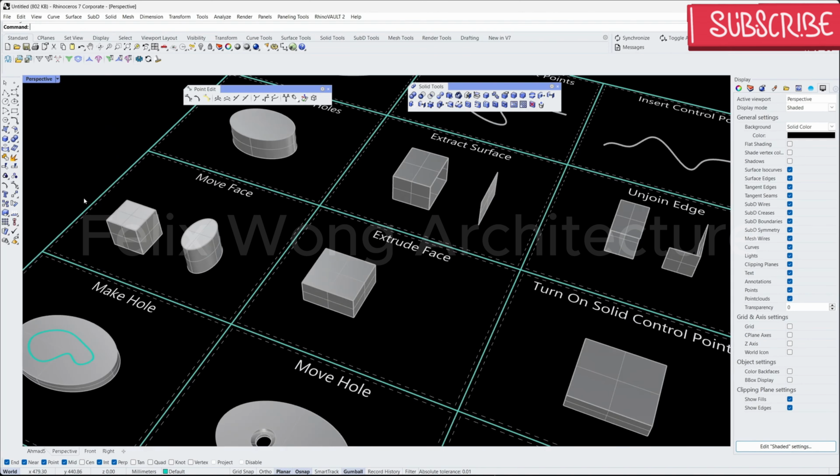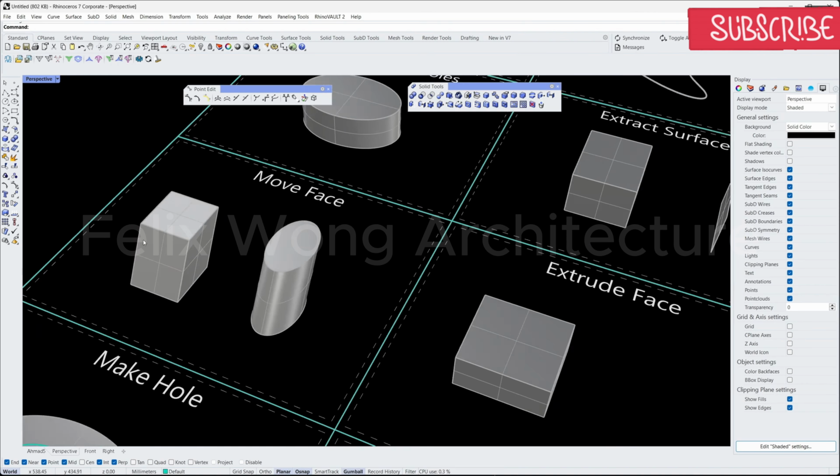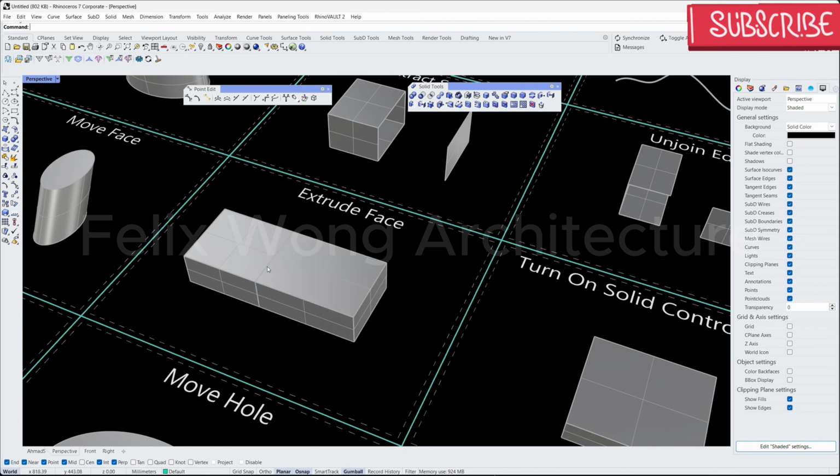To move a poly surface face, choose the Move Face command. Select the face you want to move. Press Enter, specify the direction. Choose Extrude Face to extend a face. Select the face you want to move. Specify the direction and the distance.